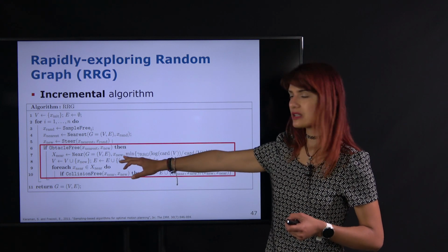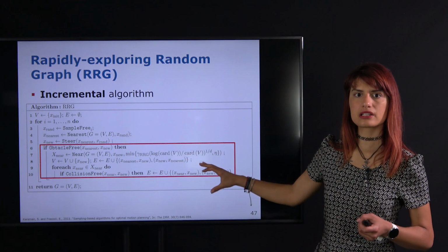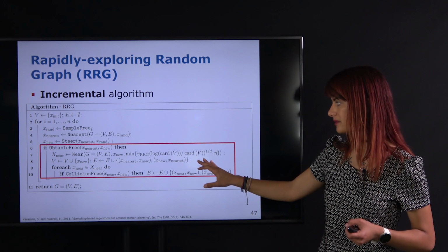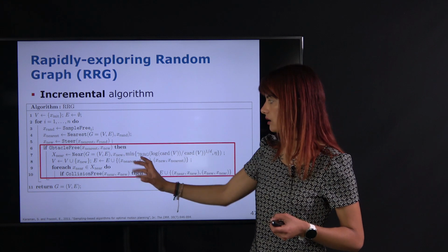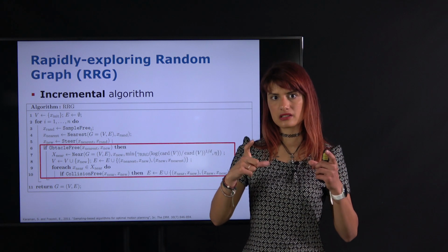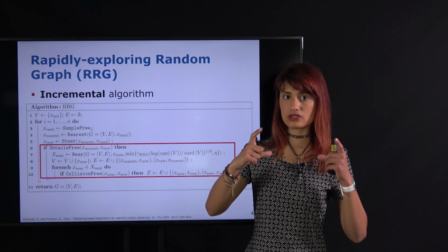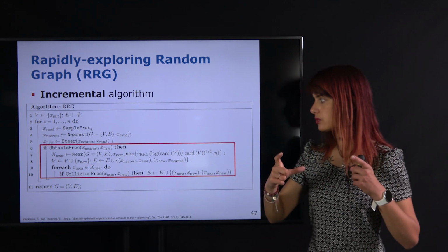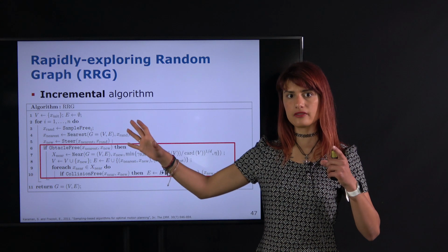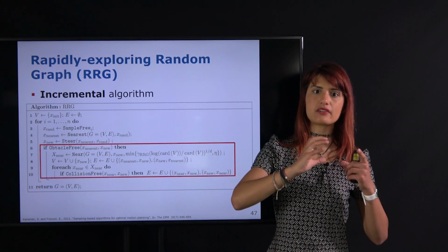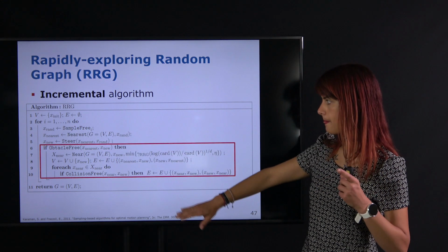This radius is really the key insight as to what gives us asymptotic optimality. So what we want to do is design our radius of connectivity checks in order to take these ideas from random geometric graphs that give us properties of asymptotic optimality.